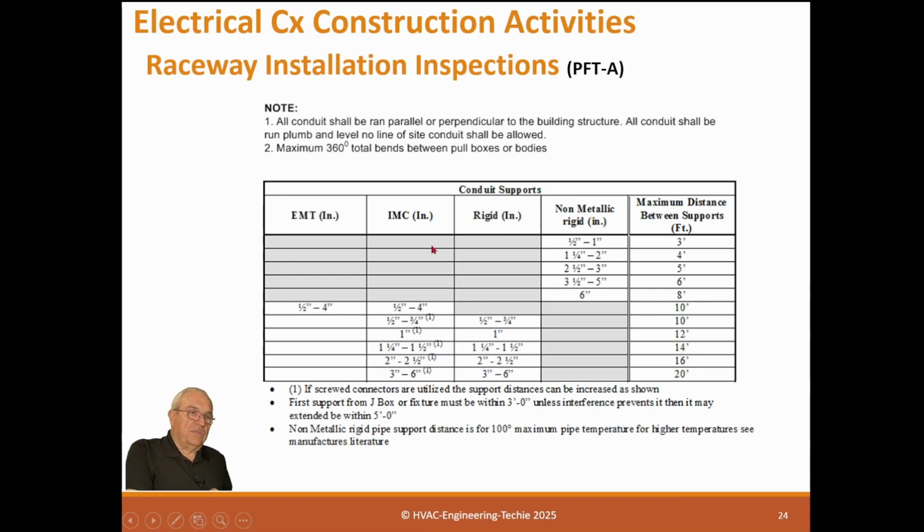All right, now this one's maybe a little detailed, but I had to put these together to help inspect. When a contractor builds this raceway system, puts his conduits up, he'll put hangers up, and there might be trapeze hangers. And with trapeze hangers, there's a problem: how do you know if they are adequate or not? I've been on jobs where the trapeze are bowing 2 or 3 inches, which means they're way overloaded.